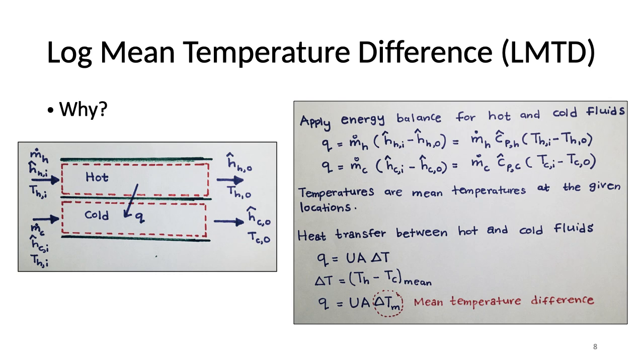There are two main relations that represent the heat flow rate of a heat exchanger for analysis or modeling. They are m Cp delta T and UA delta T. In order to find the mean temperature difference delta T, we use the LMTD method. Next, we can see how the equation for LMTD is derived.